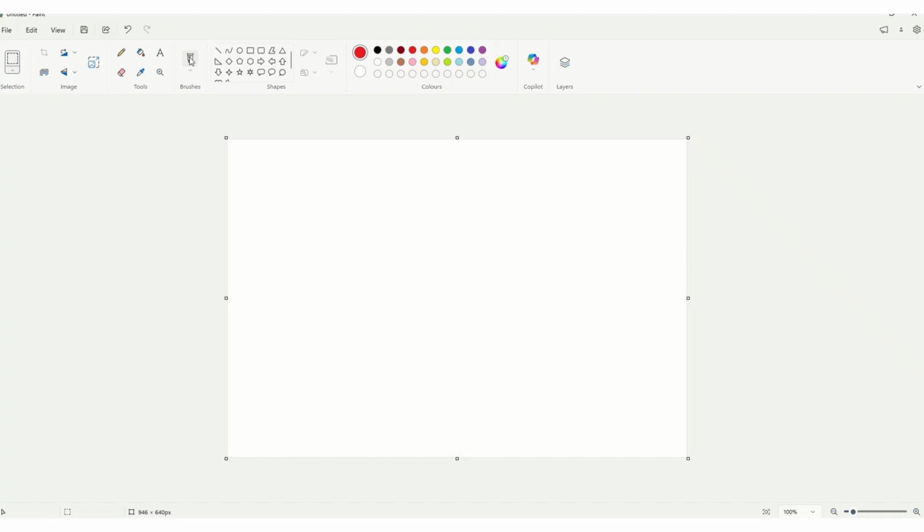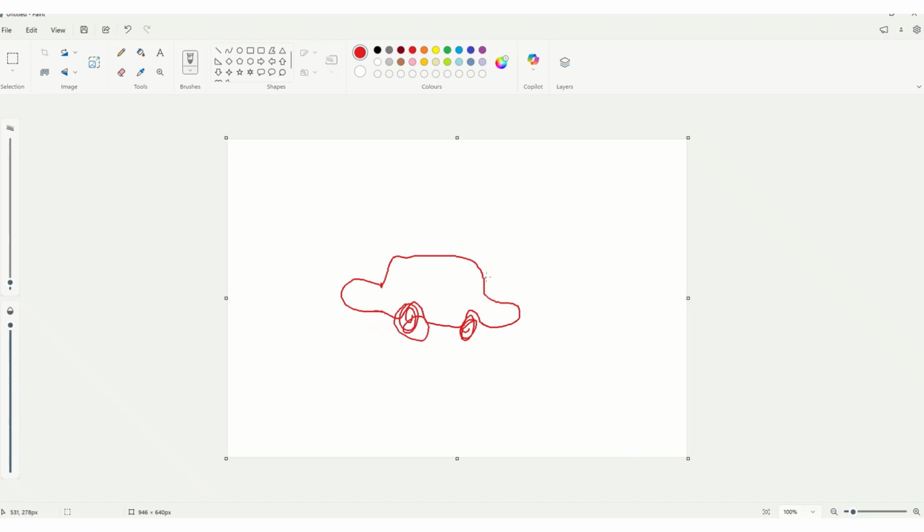If you have an automobile like this, and you have to design an antenna to install at this position, you have to consider this area as the ground plane. You will get the CAD model for this entire structure, but you have to cut this much part for the simulation areas. You don't have to consider the entire CAD, only a small part.